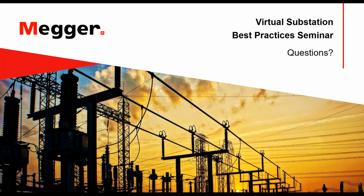Good afternoon, everyone. When we talk about residual flux or residual magnetism, any test that has to do with the core of the transformer would get affected by that. Some of the tests that would get affected are tests like excitation current, because you are trying to measure the core excitation.